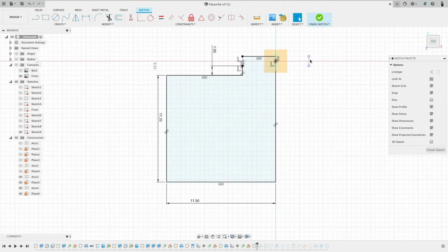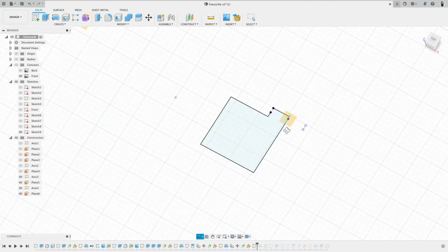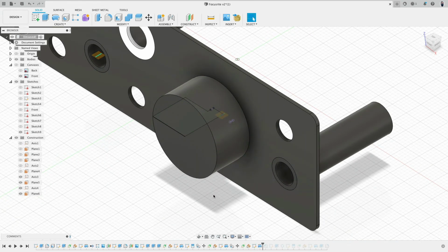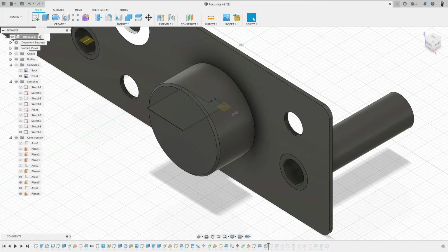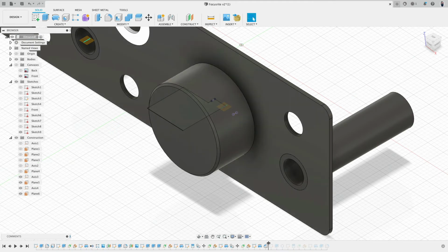Here are the two lines we found. We are intersecting 1 millimeter of a distance. Everything is horizontal and vertical. Also here, the dimension divided by 2. Very good. There is the length for this. And then a rotate command. The next step is actually quite fun. Then we will chamfer that edge, very small, just 0.5 millimeter.